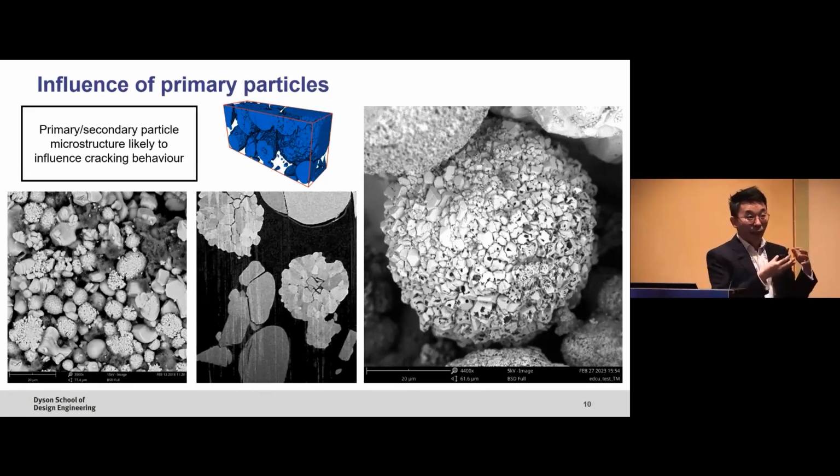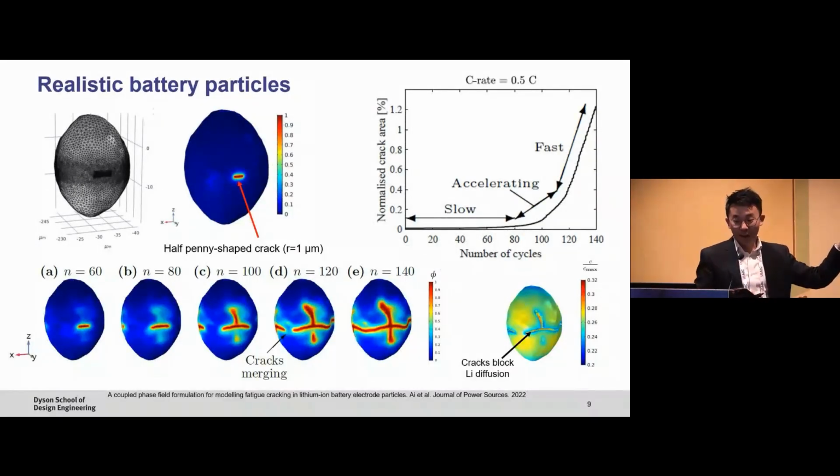So we have applied our fracture models to the cathode, and we get generally good agreement from a qualitative point of view. And also, if you can see from our phase field model work, qualitatively speaking, it does match up. But I do think on the anode side, there still needs to be work in terms of understanding how graphite actually fractures. I think silicon is probably a good proxy, because silicon is quite a brittle material when you look at the Young's modulus properties. But the challenge is your model is only as good as your input parameters. And actually, there's not a lot of people that provide fracture toughness measurements of these materials. So it's a call to the community to not only focus on electrical properties, but also mechanically characterize the system.